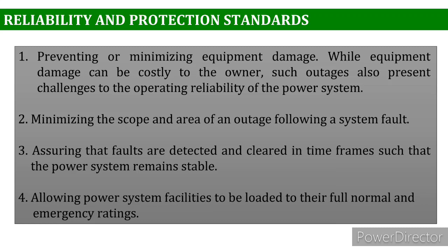Secondly, minimizing the scope and area of an outage following a system fault. Along with that, assuring that faults are detected and cleared in a time frame such that the power system remains stable.